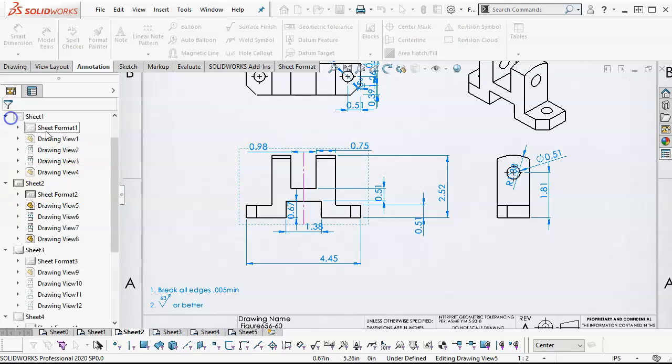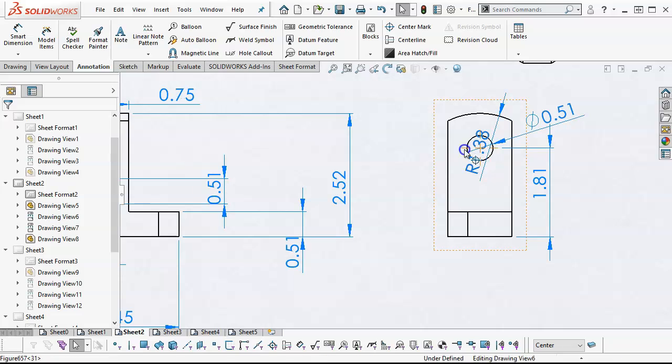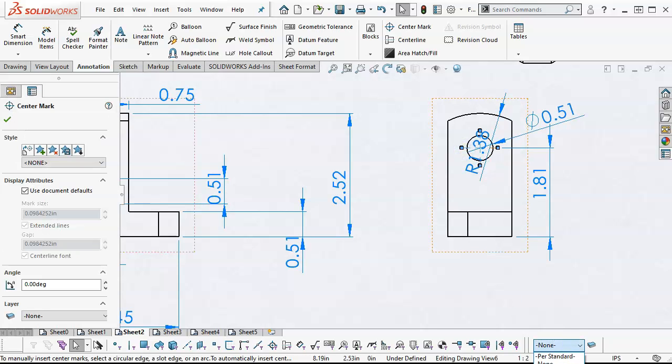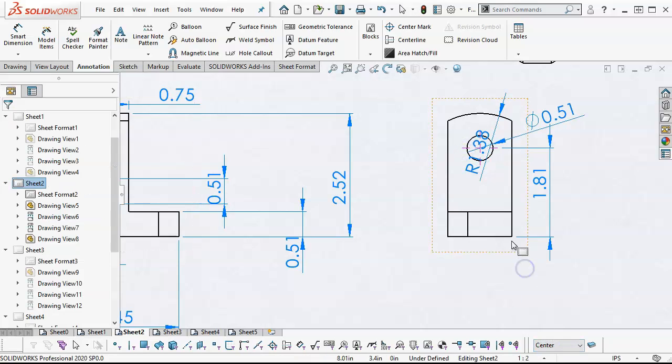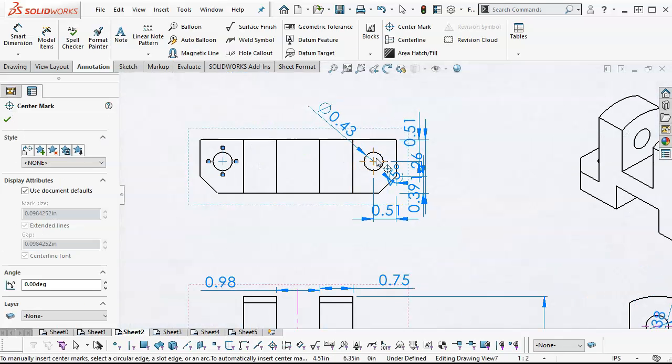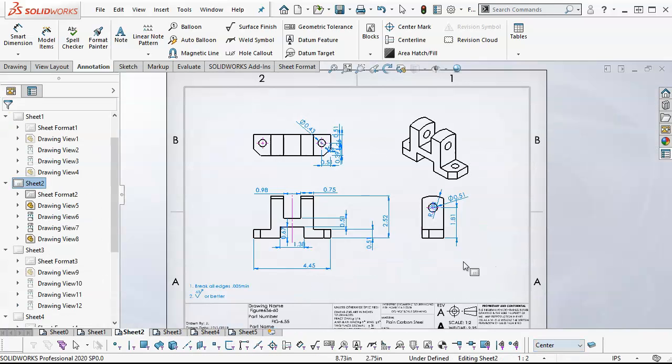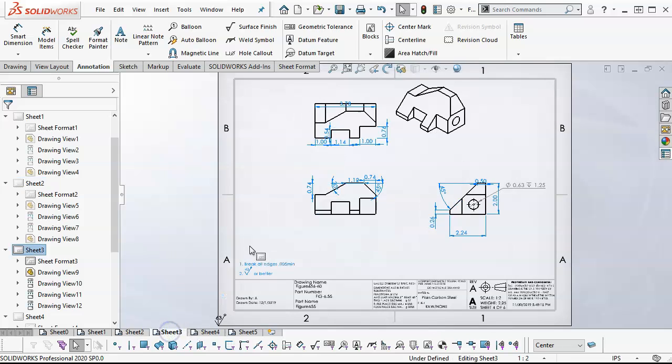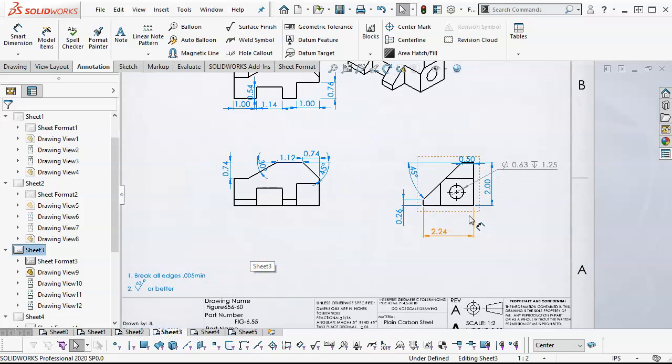We'll come over to the center mark, highlight it, change it over to center, and the 2 center marks. So we're generating a little bit of contrast as we position these numbers and get everything a little more refined as we go through the detailing process. Then it'll have a little more visibility, readability for our objects.